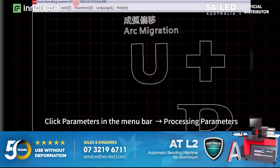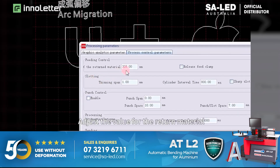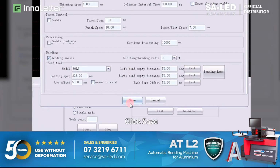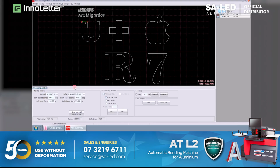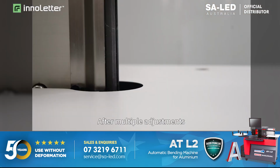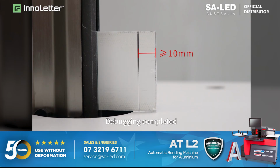Click Parameters in the menu bar, Processing Parameters. Adjust the value for the return material. The smaller the value, the shorter the material return. Click Save. Select the shorter path for the test. After multiple adjustments, until the length of the front and waist is more than or equal to 10 mm. Debugging completed.